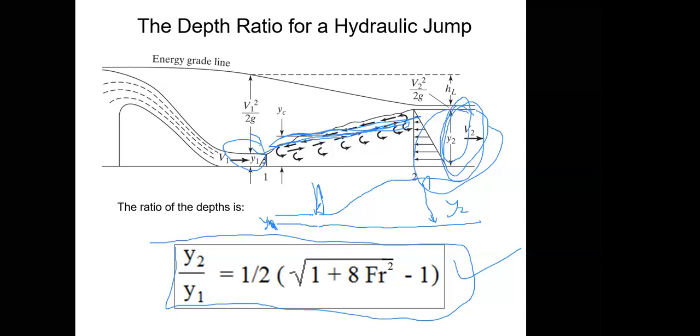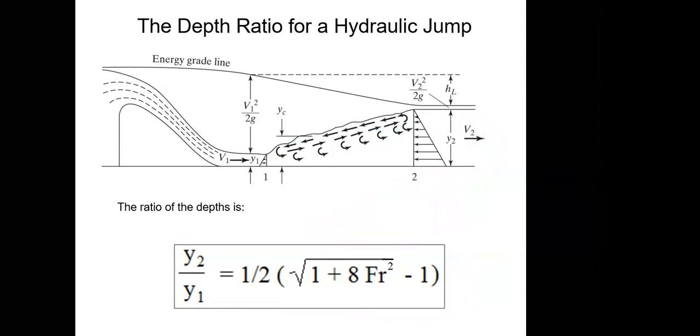Okay, any questions at this point? Good, let's continue. But in this case, Pak, Y1 is the critical Y? Not necessarily the critical Y. Not necessarily any Y that you. I mean, if you have experienced this, you actually want to avoid this hydraulic jump, or at least you want to anticipate this, and we can anticipate this by using these equations. The Y1 is the source. This happens when you have a change of the Froude number from less than 1 to greater than 1. Okay.